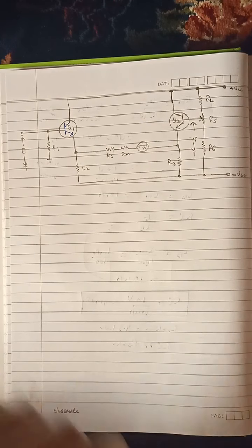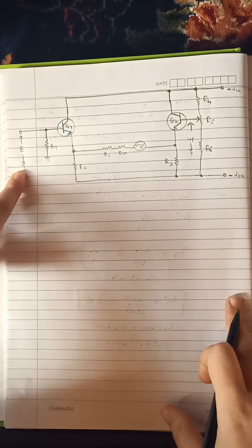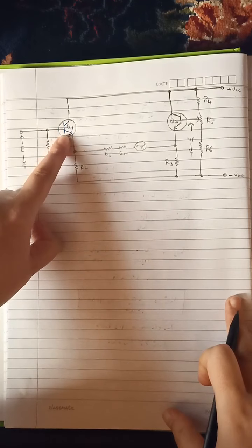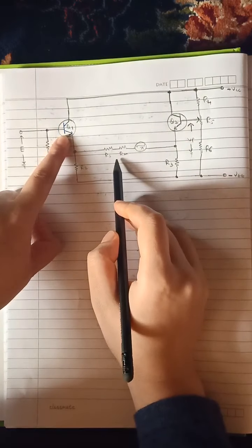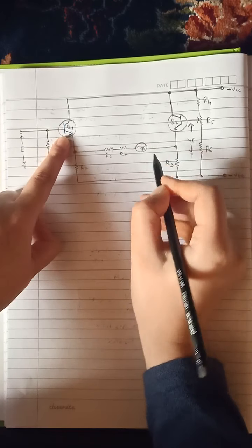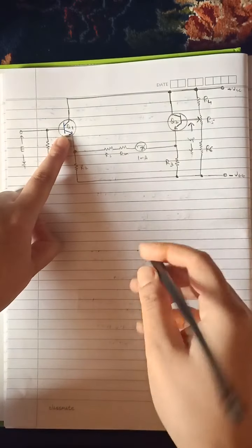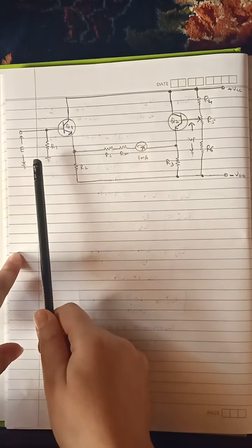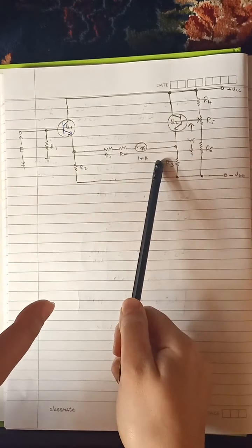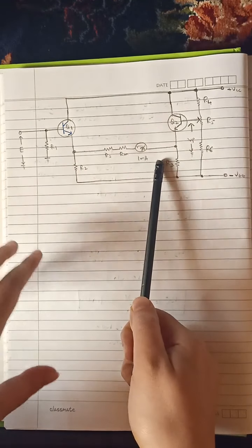Now, when no input voltage is applied to this voltmeter, that means this E is equal to 0, the base voltage of this transistor Q1 is adjusted to give a reading on this meter, which say here is a M meter with maximum deflection of, say again, 1 milliamperes. That means it should be such that when this is equal to 0, the meter should be showing the reading obviously equal to 0. Then only we can say there is a 0 voltage.